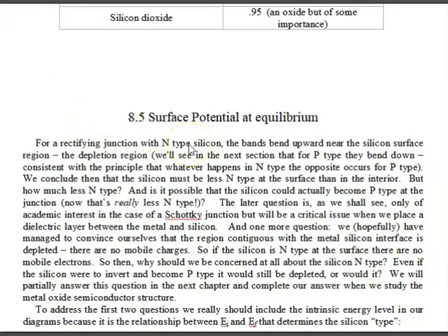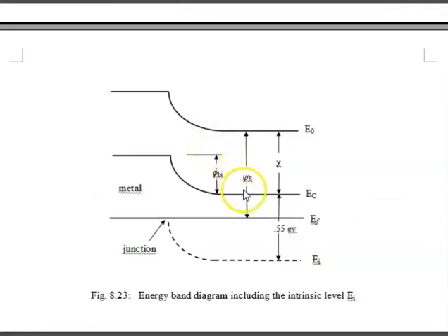The point here is that because we have a depletion region W, which does not contain mobile charge, we have a region in which the doping in an N-type silicon is much less. In fact, it's pretty close to intrinsic compared to the interior. And you can see that here, the doping in this region, this is the depletion region, and it extends a width W from this point, which is the metallurgical junction, until the interior, and everything to the right here will be known as, actually three terms, I think, quasi-neutral.